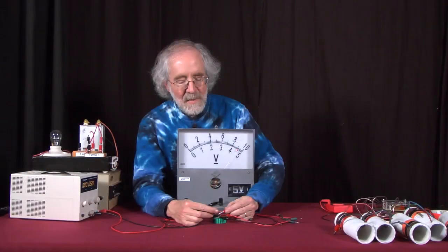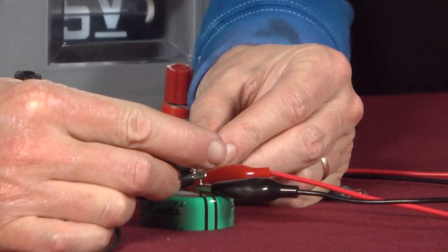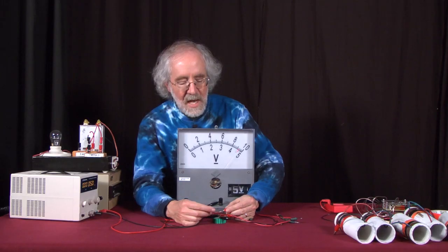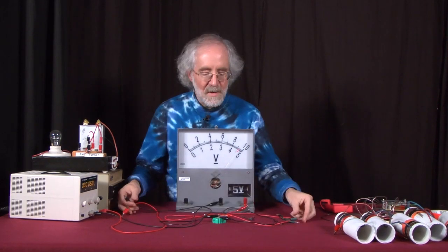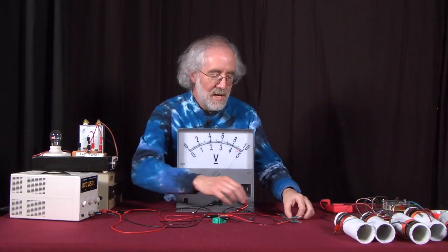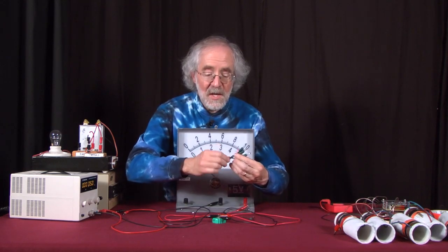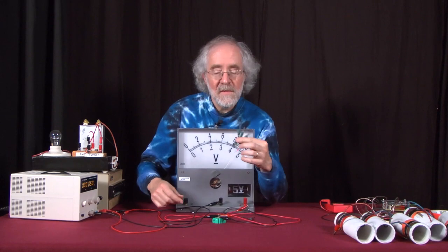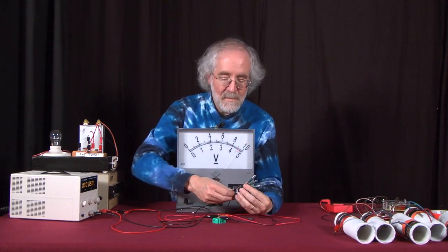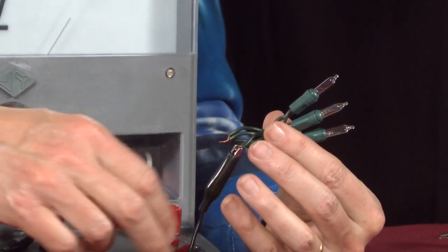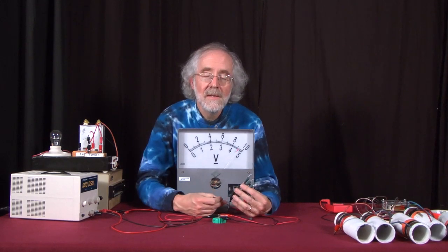So I'm going to charge this capacitor back up again. So now it's charged up to 5 volts. And I'm going to hook it up not to 1 light bulb, but to 3. So I'll hook it up to 3 light bulbs connected in parallel. And as we learned in a previous segment, that means the equivalent resistance is less. So these light bulbs will draw more current.